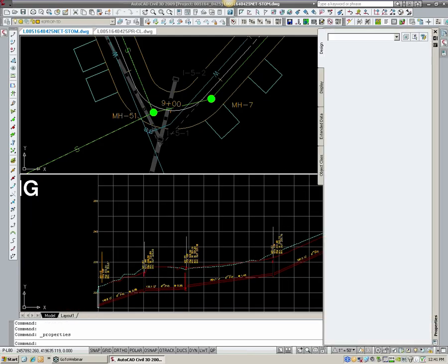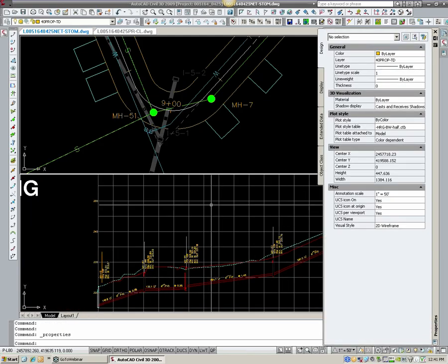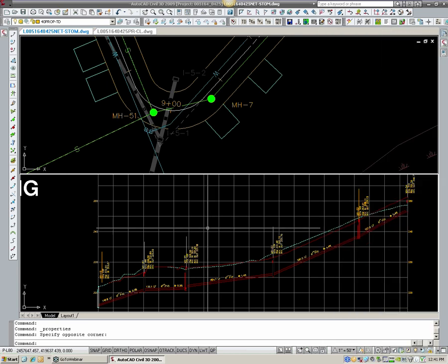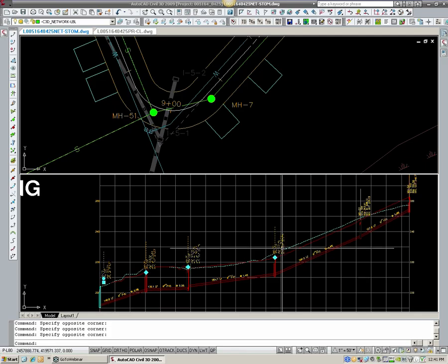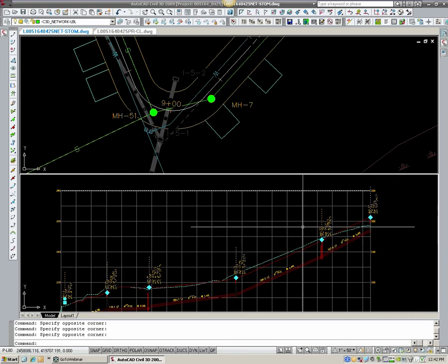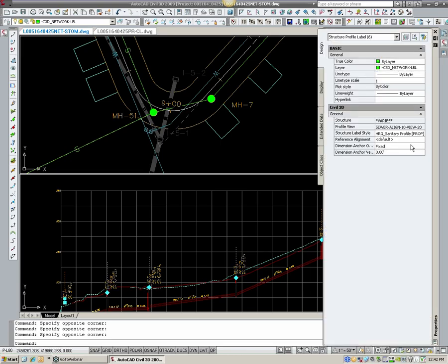Notice when the AutoCAD Properties palette is open. So it's open here, but docked. And I'm going to actually have it auto-hide. Look at the delay I get every time I select the label. I get a little delay. That's what I'm always talking about when I'm telling people, keep your palettes closed. They add lag to the system. If you're okay with that delay, keep it open all you want. But I'm not, so I usually keep this closed. I select the stuff, I open up my AutoCAD Properties palette, do what I need to do, and then I shut it down again.